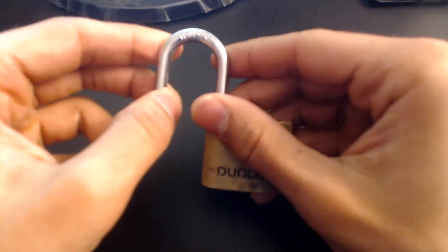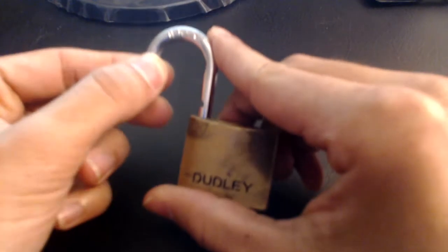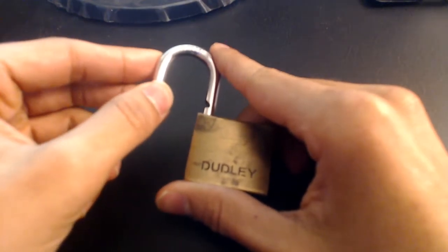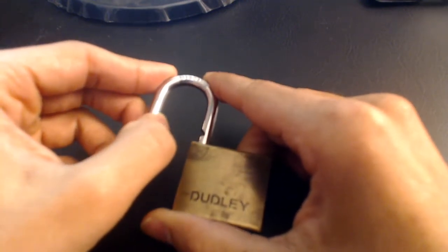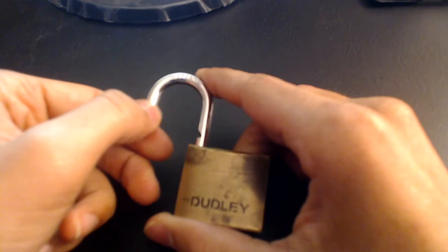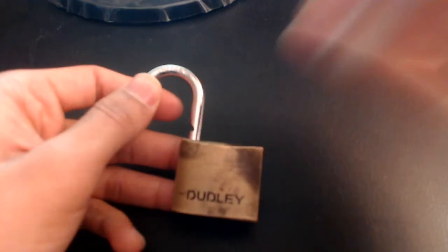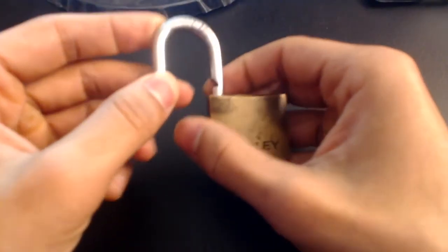The material is then either machined or cold worked down to this necessary diameter. If it were to be cold worked, it was likely extruded into its round shape, or bar drawing is another common technique used to form specific diameter round stock bars. The length of the shackle while it is straight would then be cut, and then it would be bent into this U shape you see here.